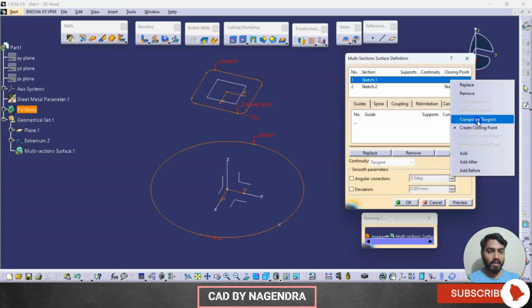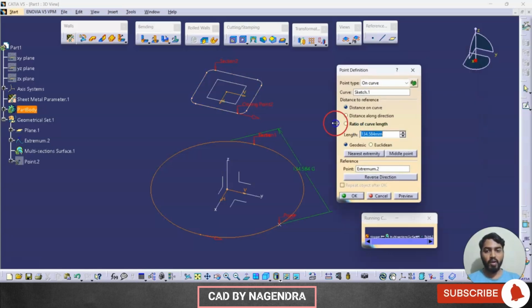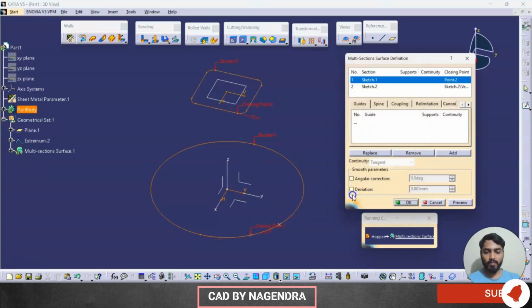So right click with the mouse and create a closing point with reference to the existing closing point, and say OK. What is the importance of these closing points? As before with the conic hopper, we created 2 points manually. Wherever the sheet is going to join, that is the particular selection of points where we create closing points. Same in this case: where we have these closing points, exactly there, after bending, the sheet will come and meet. So I have created 2 closing points.